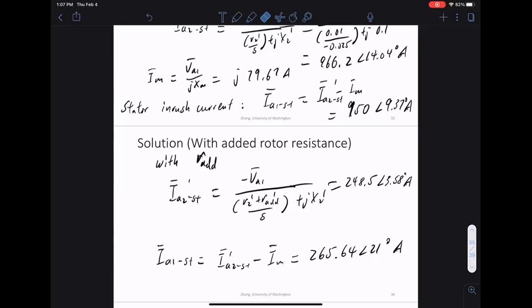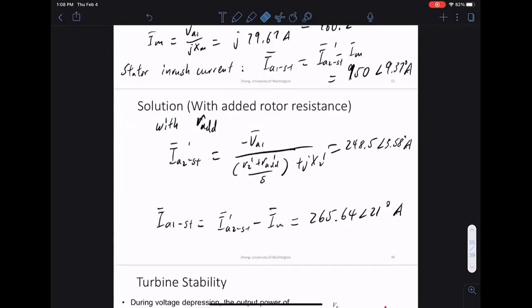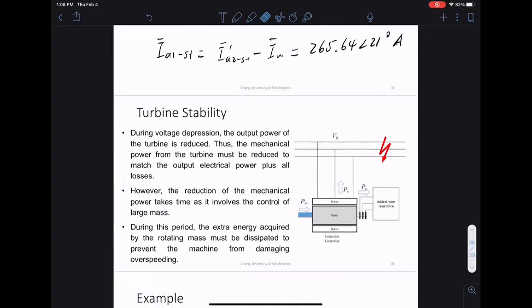Okay, so the last thing we'll see for the type 2 turbine is again stability. Turbine stability means, for us, the fault we worry most about is, again, that something happened to the grid side. Okay, so the grid side goes away. That's the thing we worry the most about. So here, this lightning bolt means something happened to the grid, that causes a large drop in voltage.